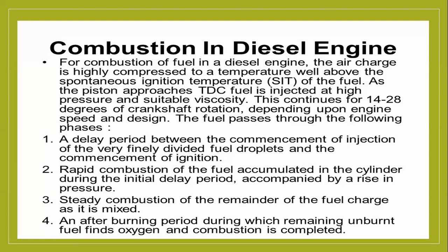For the combustion of fuel in a diesel engine, the air charge is highly compressed. They will not tell you diesel-air mixture, here only the word air. The air charge is highly compressed to a temperature well above the spontaneous ignition temperature.